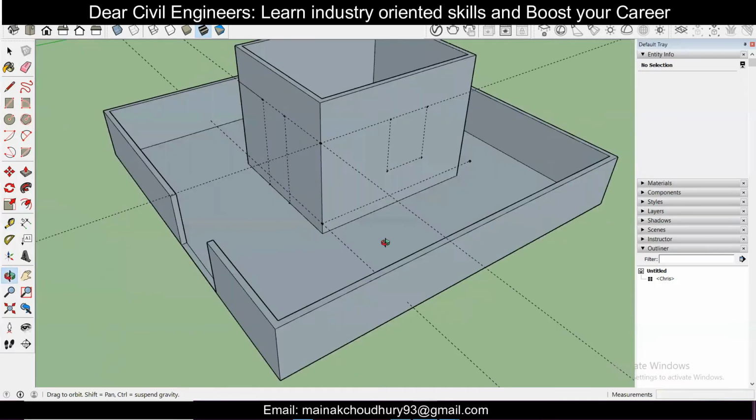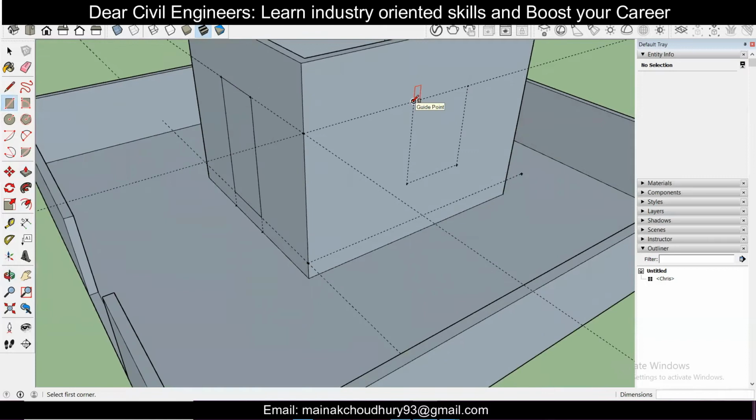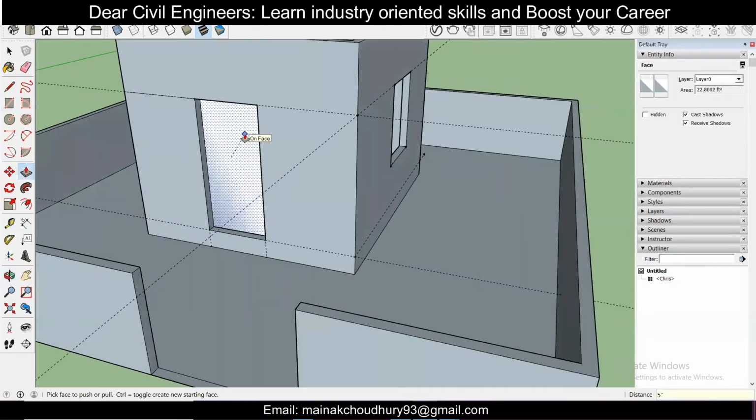And let's just create the opening for the door and window first. So first of all, we'll use the rectangle tool and draw a rectangle here properly. And after that, also draw a rectangle here. Use the rectangle tool again and draw a rectangle here properly. Use the push pull tool to select this, and we know this wall thickness is 5 inches. So we'll provide an inward offset of 5 inches like this. Similarly for the door, 5 inches like this.